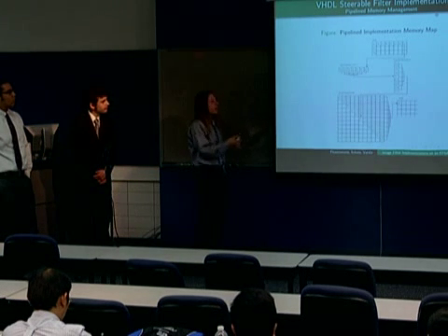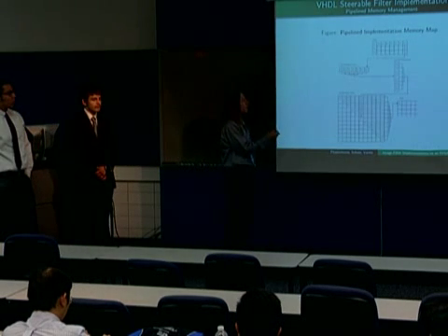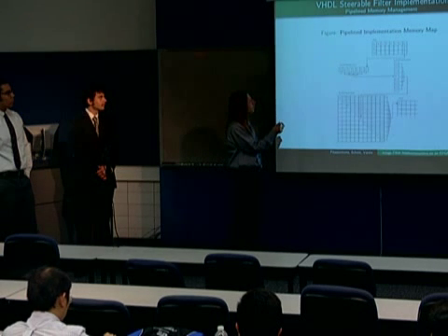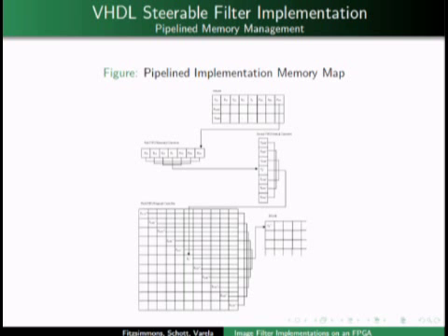And here's how our pipeline works. This is the memory management and just the general flow of pixels. So you can see here, this is the first row of the image. And once you get to this pixel, the 7th pixel, you can convolve, which gets stored there. This is the last pixel. Then it allows this pixel right here to be convolved and stored in this next FIFO. This FIFO is the size of the mask times the width of the image. And basically, it takes these pixels on this row and convolves them and sends them to the next FIFO.